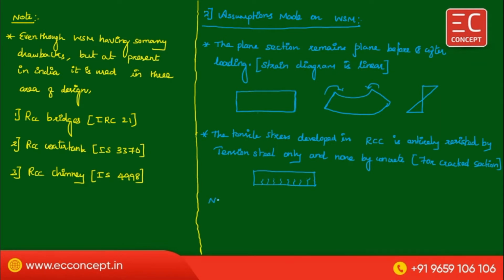Take a note. First point, for an uncracked section, the tension force is taken by tensile steel as well as concrete.